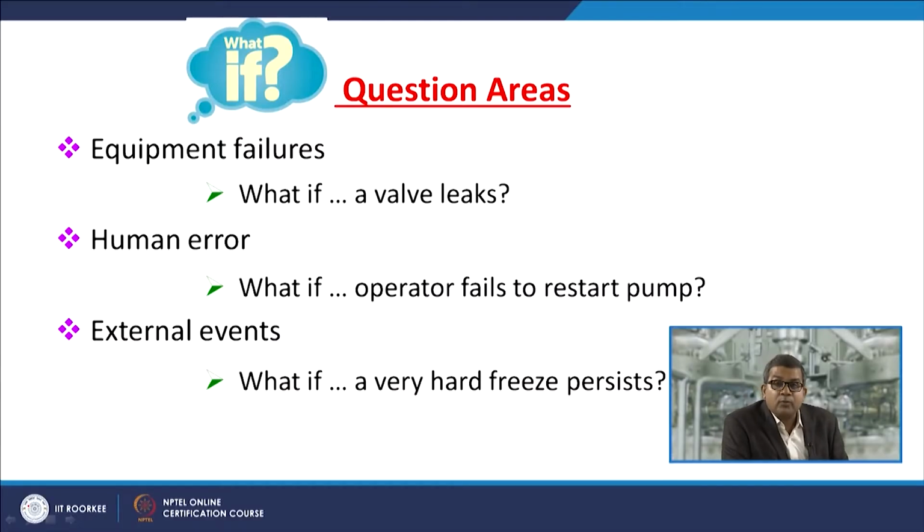There are sample questions. Equipment failure: what if a valve leaks? Human error: what if the operator fails to restart the pump? External event: what if a very hard freeze persists or a storm occurs? So you need to carry out the what-if analysis. These are the sample question areas. You may be highly localized in terms of questions. What if the raw material contains impurity? Sometimes the impurities are dangerous. Like, suppose you are dealing with a chemical which is 95% pure.